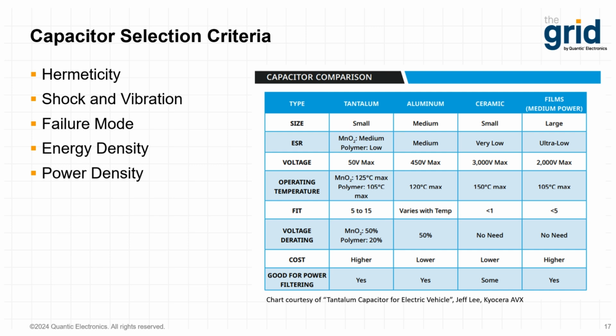Now, although hermetic is commonly thought of to mean airtight, hermetic really means that gases and moisture cannot penetrate the capacitor and they cannot escape from the capacitor as well. There is a MIL standard, MIL standard 202, method 105, condition D, and this specifies a 100,000 foot altitude test. If a capacitor can pass all the test parameters within this MIL standard, it is considered well suitable for high altitude applications.